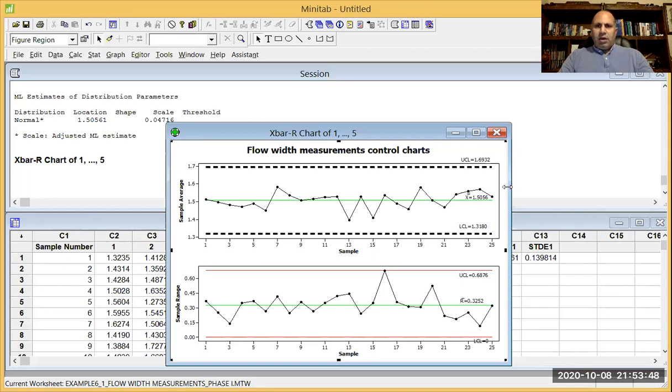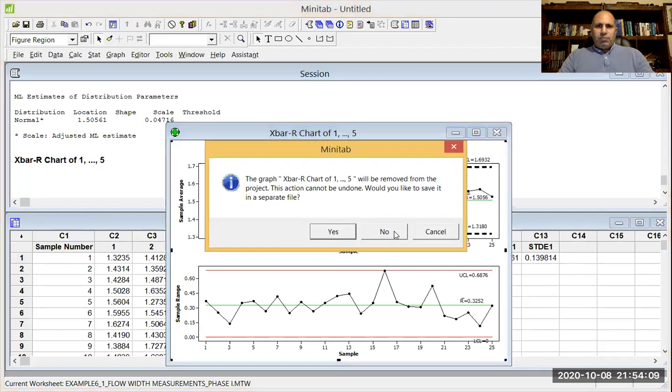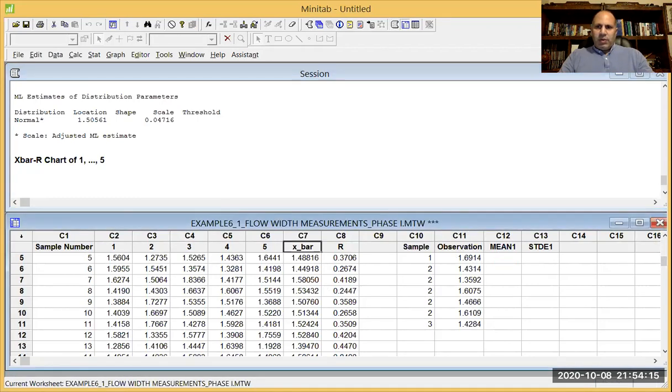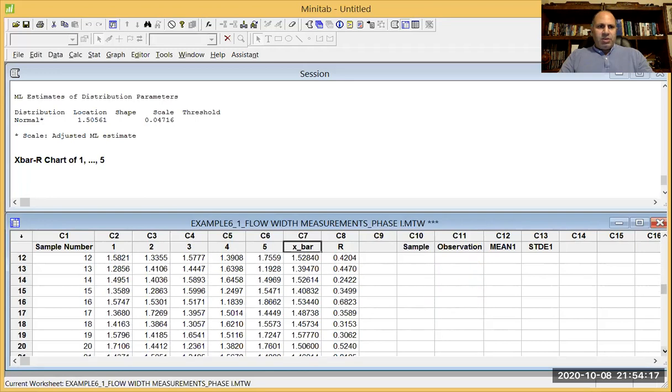Basically, we have the process mean, process standard deviation, or R-bar value, which should be divided by d2. Now, let's do a phase 1 implementation. For this purpose, in this example, I had 25 samples, as can be seen.